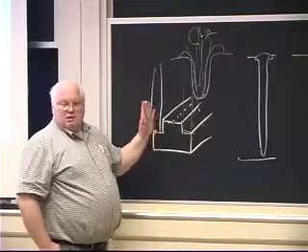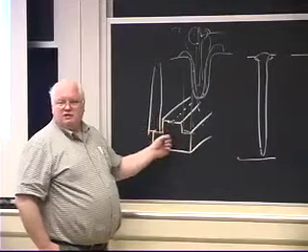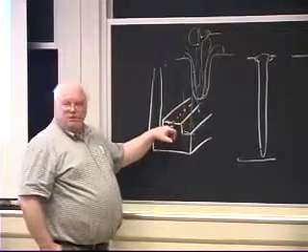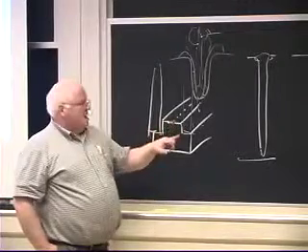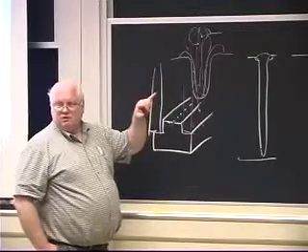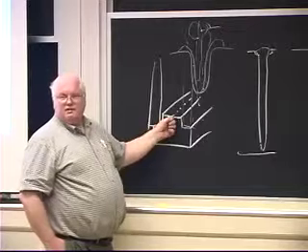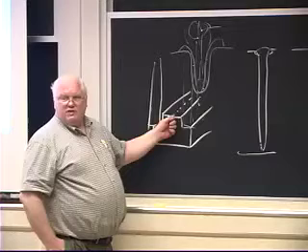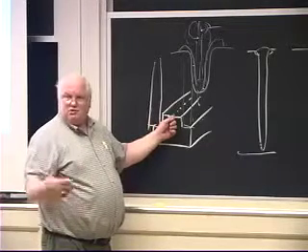But in like the mid-1980s, I had a number. They make 300 million feet of this stuff a year. There was a place in Illinois that had 10 lasers that were all welding this stuff, with a continuous laser beam, but it made an intermittent weld because the process was inherently unstable. The power of 10 to the 7th, which is what they focused it to, would come in, couple with only 10% efficiency, which would be 10 to the 6th watts per square centimeter, which is